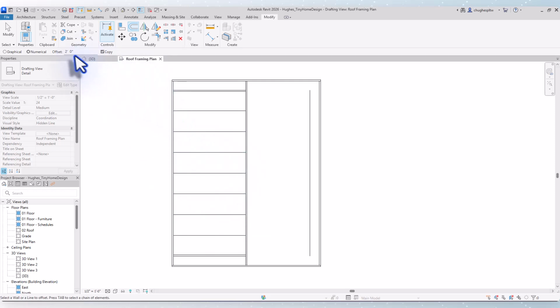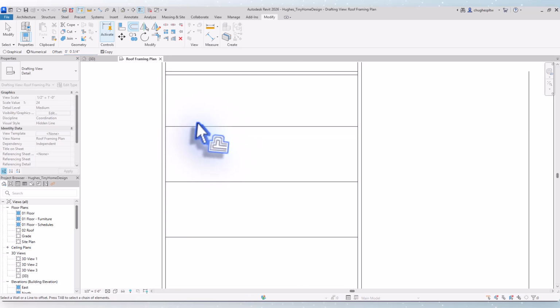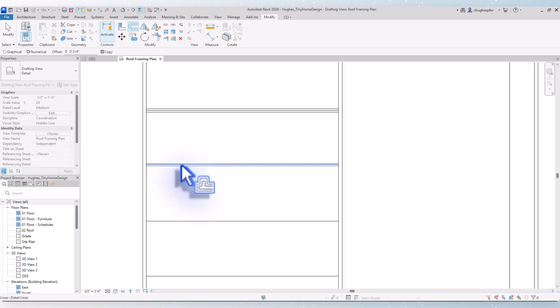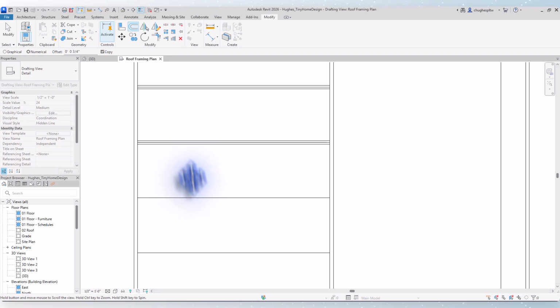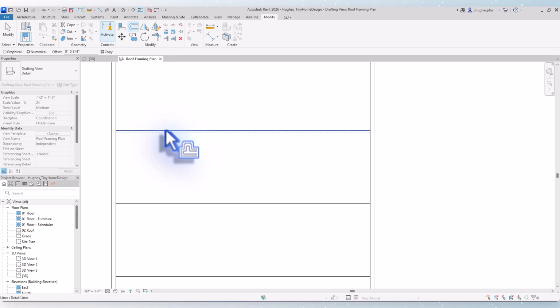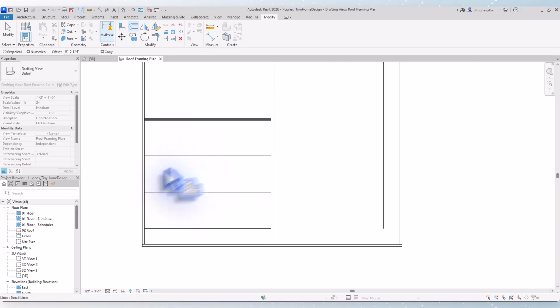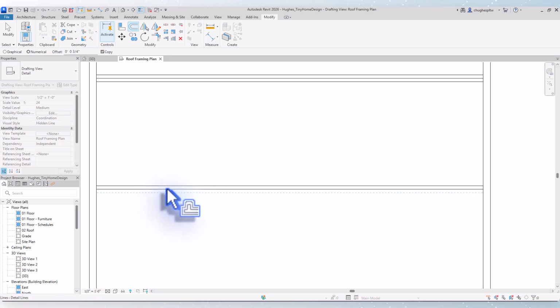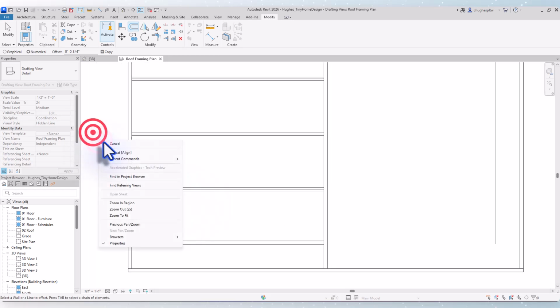framing plan here. Now, we do need to represent the thicknesses of those rafters. So I'm going to do a 3/4 inch thickness one more time. And on each one of these lines, on each side of it, I want to go ahead and place an offset line. Got 2 more. Again, just make sure, watch where those blue lines appear, and that helps.